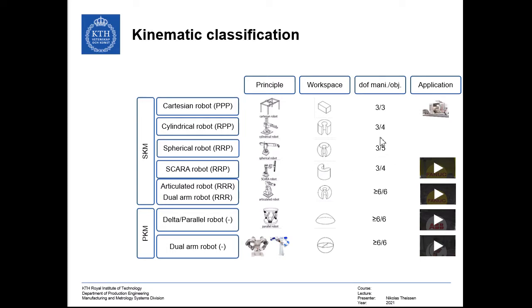And once again, while it has 3 actuatable degrees of freedom, this results in 5 degrees of freedom on the object to be manipulated, because with the 2 rotations and the translation, you can put it into any position, but now you can also change 2 degrees of its orientation. So you might think of Euler angles, which are represented in terms of the rotations about the x, y, and z axis, or the rotation about the z, y, z axis, which is a common way to express this.